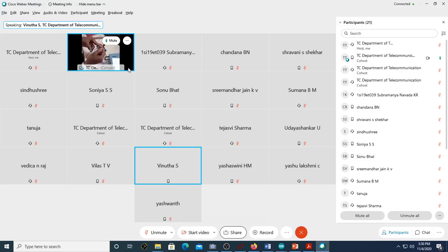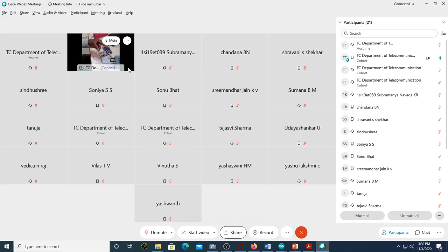The middle one is output, that is either it can go to VCC or ground depending on the switch position. And this left side is VCC. I have got ground, VCC on either side. The middle pin is going to your buffer input, to the Arduino.